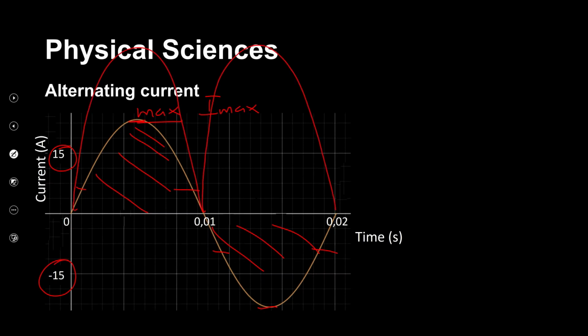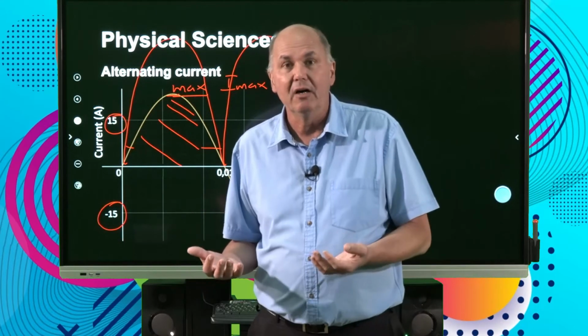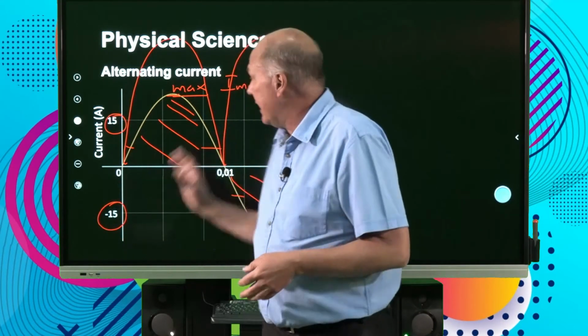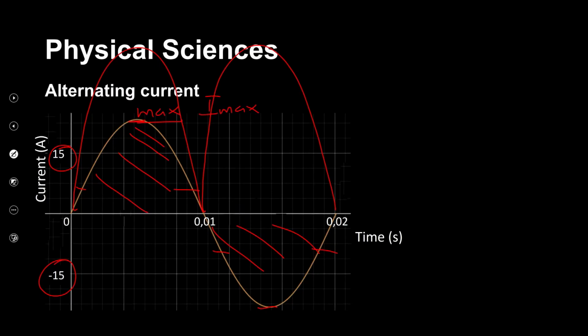And we can now say, we've got the square, but we don't want the square. So what we can do now is to get the average and say, well, let's add these together and then let's take the square root of them. And so if we take these and add them together and divide by 2, so we take I squared and we take 2 because we're getting an average, because we've got the values, minimum, max, and then we'll say, well, let's take the square root of this whole thing. And if we do that, then we'll get Imax over the square root of 2. And that is called the I root mean square.